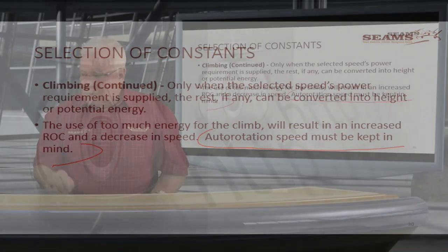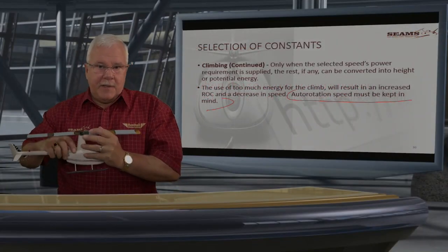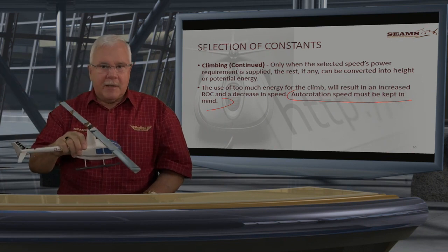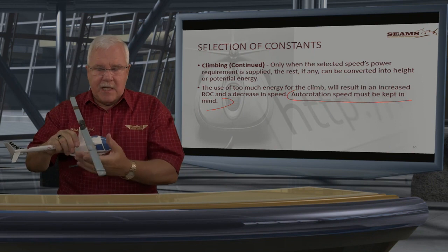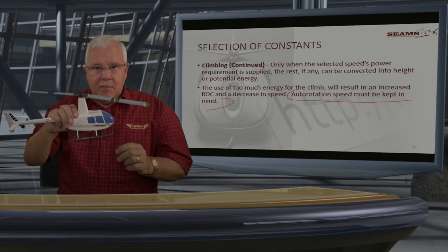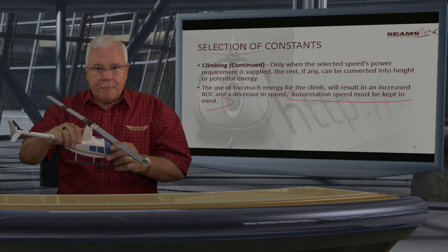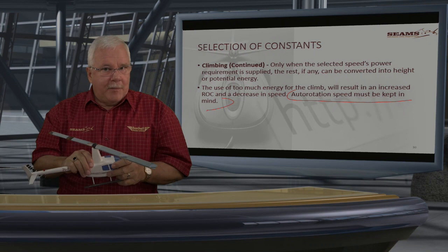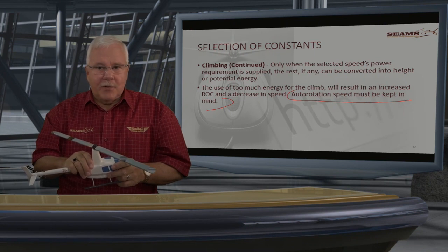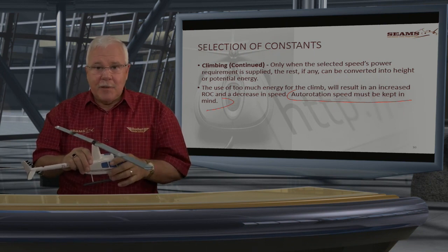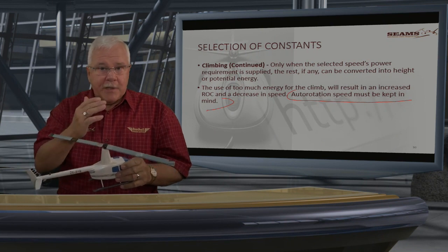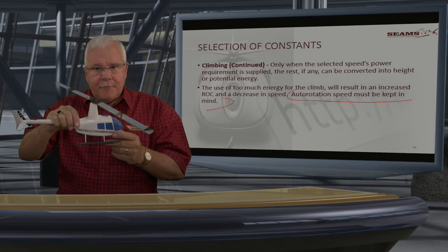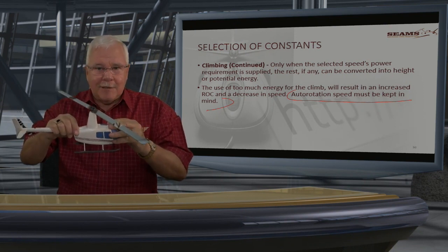I said, look, you can really take your helicopter and decide, I'm just going to do a vertical climb. Because I'm not going to climb at, let's say, 65 or 70. I'm just going to climb vertically. But remember, when you want to auto-rotate, you don't want to auto-rotate vertically down, you won't be able to use that as such because you will be in the void area, and this is where you will get recirculation and vortex ring or settling with power. So you actually would like forward speed. All right? So keep in mind the forward speed.